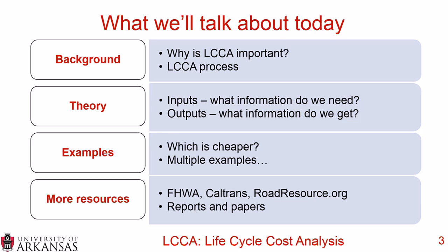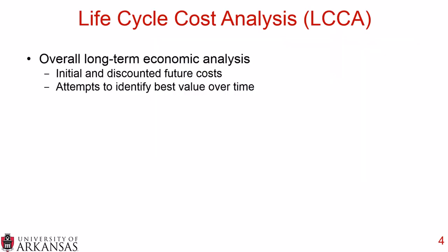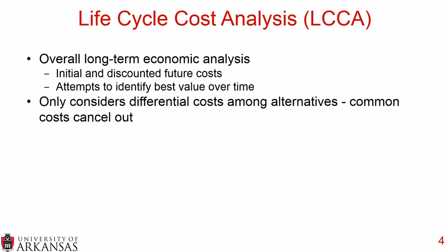So let's jump into why a life cycle cost analysis is important. Well, an LCCA provides an overall long-term economic analysis. It includes both initial costs and discounted future costs. And what an LCCA does is it attempts to identify the best value over some sort of time period. One nice thing about an LCCA is it only considers differential costs among alternatives, so any common costs cancel out, and this can simplify things pretty nicely.